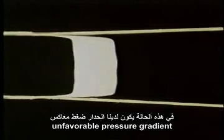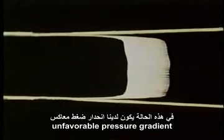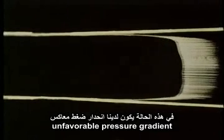On the other hand, in a divergent channel, the boundary layer becomes thicker, with a corresponding decrease in wall shear stress. In this case, we have an unfavorable pressure gradient. The increasing pressure associated with a decreasing mainstream velocity decreases the velocity in the boundary layer, so velocity gradients and shear stress are less, and the boundary layer is thicker.